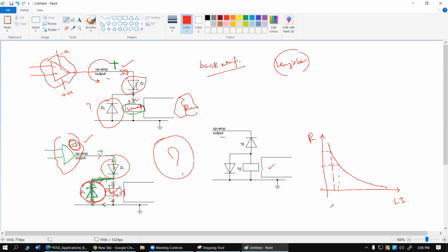But it is important that we must have access to a calibration curve at the beginning. And how can we do that? By doing an experiment with this device, recording some exact numbers out of this device, and then plotting that on a graph, and that gives us access to the calibration curve. Without having a proper calibration, any device is useless.